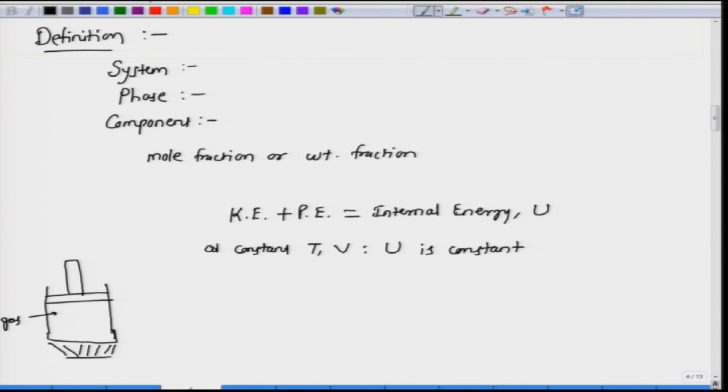Right. So, it is easy to see, if I add heat the gas tends to expand, and as the gas tends to expand the pressure builds up inside, right. The pressure inside becomes higher than the outside pressure, and so the gas will push the piston outside, and this will continue until when? Until the inside pressure becomes equal to the outside pressure. So, if you heat a little bit and take away the heat, the piston will move until the inside pressure becomes equal to the outside pressure, because that is when the equilibrium is established, right, the mechanical equilibrium, right.